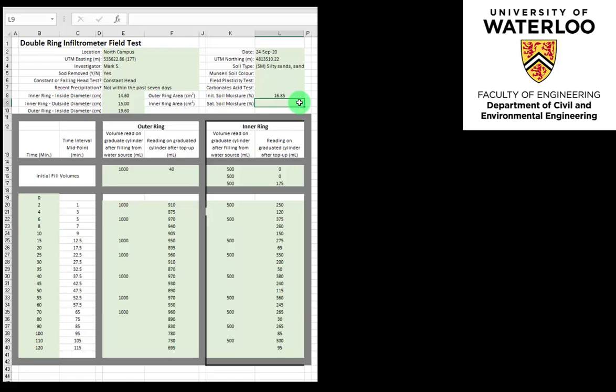The saturated soil moisture content was determined by emptying the E-horizon sample into a permeability testing column and compacting it. A hydraulic gradient test was imposed across the compacted soil. When water flowed out of the bottom of the sample at the base of the column at a steady flow rate, the soil sample was removed and massed. This was considered the fully saturated moisture content. Then the sample was dried and remassed. The difference between the fully wet and dried sample conditions is representative of the saturated moisture content. Here it was found that theta S was 40.04%.